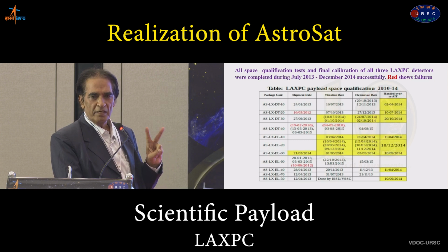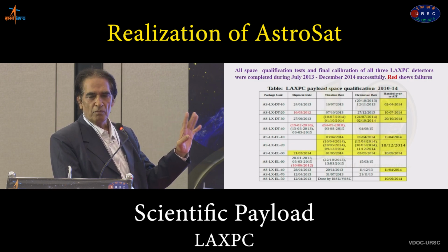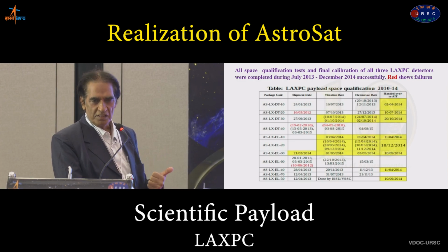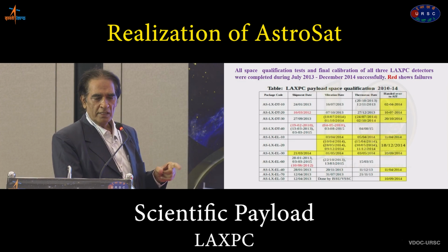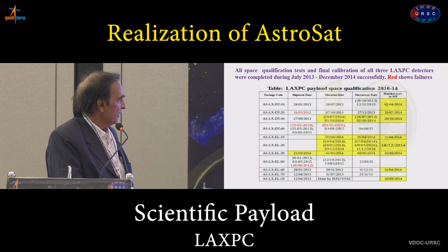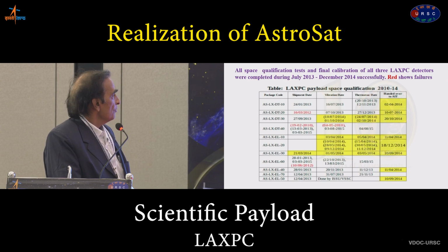And when we were calibrating with iron, one gives the clear number of photons coming from iron, the other is 0. So now we have to remove it from the calibration, bring it out, and understand. It was the gain of the ICs, because both ICs should be matching in gain. And again we changed it, and of course then we have to go through the whole cycle again. So this type of thing. Most of the tests were done from July 2013 to 2014 successfully.